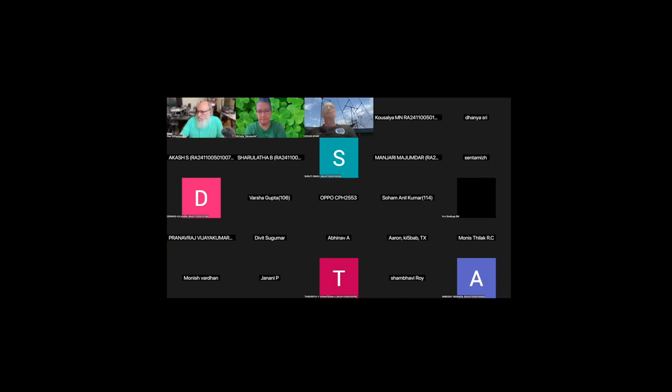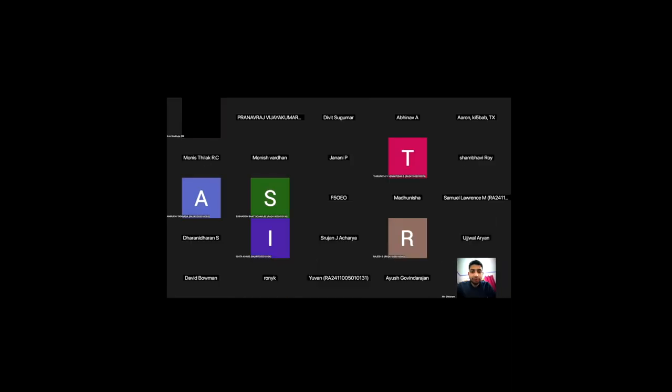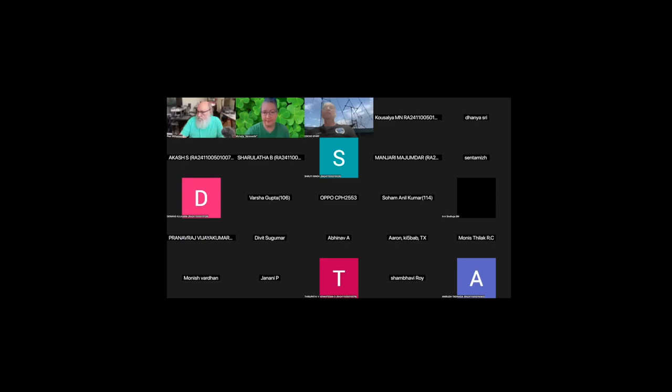Then I got that running on the LibreSDR, and I separated the transmitting of that data from another app that receives it and displays it. So now there are 2 separate apps, so that they can be on different devices. I created another application that combined the DVB-S2 transmitter and this UDP spectrum viewer into one application. So now we're doing both.